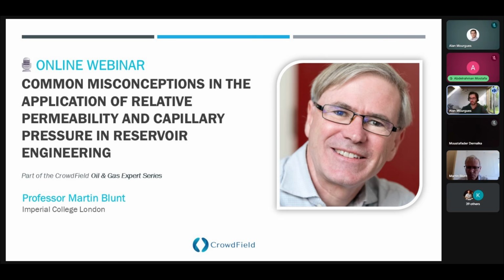I want to take you back to that primary drainage curve, and particularly focus on the zone between the free water level and the oil-water contact. Now, by definition, capillary pressure requires two fluids, and it's the difference in pressure between those two fluids across an interface. So how are we to think about capillary pressure in this zone where by definition you have just water? You have a positive capillary pressure above the free water level, but you have just the water in that region. So how are we to think about capillary pressure?